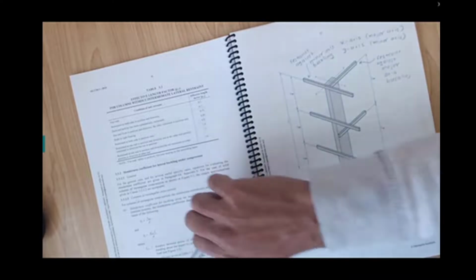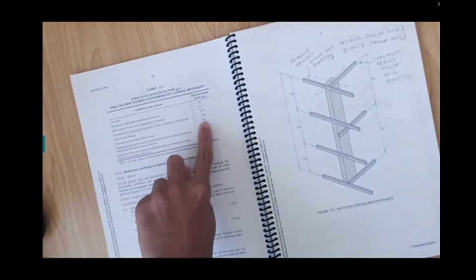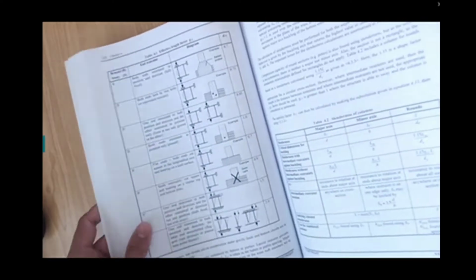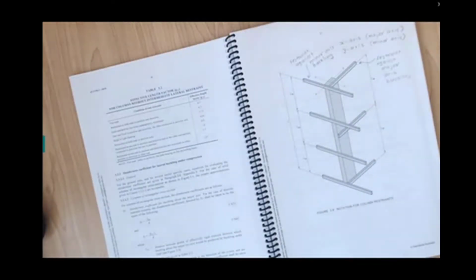All good? Okay, so that's fine. I think for our case, we are in the stud in the light framing. We are going to take this 0.9. Stud in the light framing means that we have this stud normally cut square and bearing on a timber top and bottom plate. So we have this kind of screw nail, and this 0.9 is what we are going to take, and we have this braced columns case.